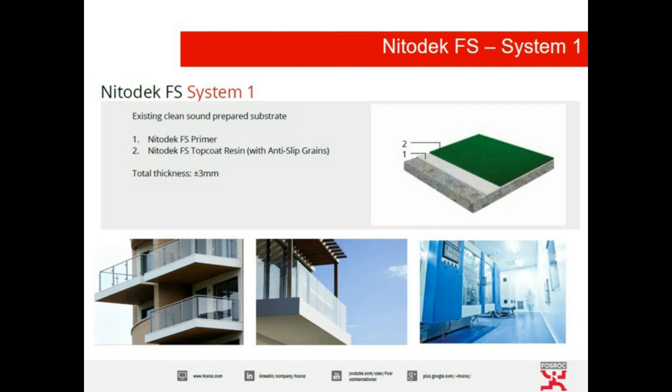Also ideal for using it outside as well. The UVR top coat that comes with it, as the name suggests, is completely UV resistant. So you could use it in a scenario where there is maybe an essence of waterproofing about it, but you're not actually having to waterproof habitable space. So you can see in the bottom left-hand image there, it's a cantilevered balcony. You don't need an outright waterproofing system there because ultimately the space underneath it is open to the elements anyway.